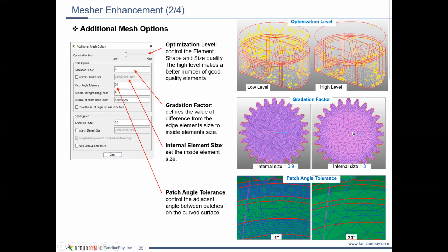Anyway, so now we get this mesh with fewer elements, but as far as the results of working with this body, you can end up with fewer elements and still have the same accuracy in the results. So that's something that you want to try out and then compare results. Make sure you're not losing any quality.